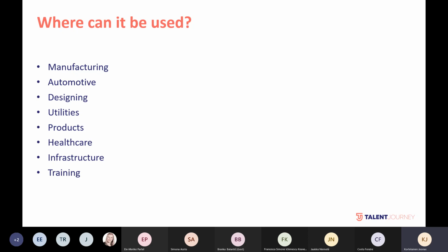You have told it that the screw holes can't move; they have to be where they are, and the shelf position or the notch or the hole cannot move at all. That has to be where it's placed. And there will be a static pressure of 100 kilos on this shelf position. So now the software will calculate the best possible shape for your brackets. So in the end, your bracket will look totally different than the first time you designed it.